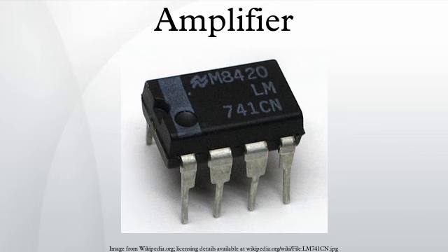The class of amplifier depends on how the amplifying device is biased. The diagrams omit the bias circuits for clarity. Any real amplifier is an imperfect realization of an ideal amplifier. An important limitation of a real amplifier is that the output it generates is ultimately limited by the power available from the power supply. An amplifier saturates and clips the output if the input signal becomes too large for the amplifier to reproduce or exceeds operational limits for the device.